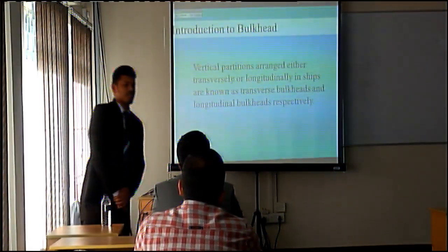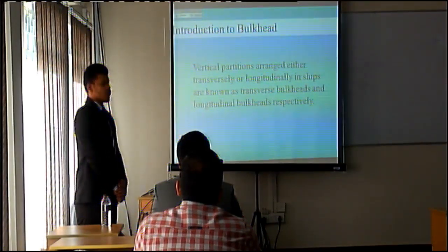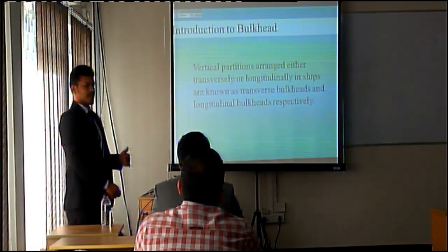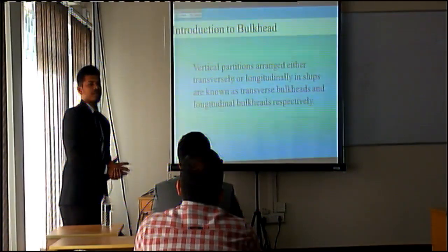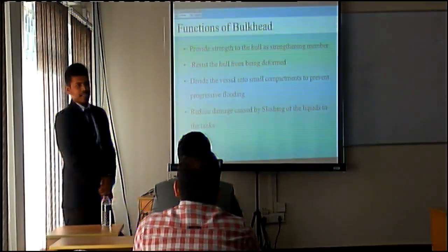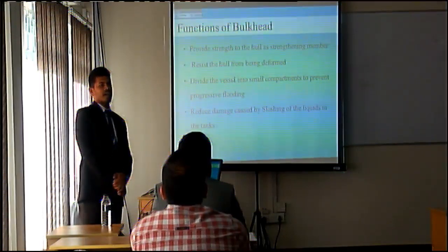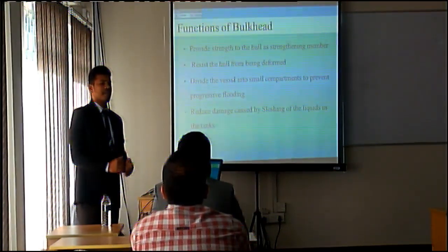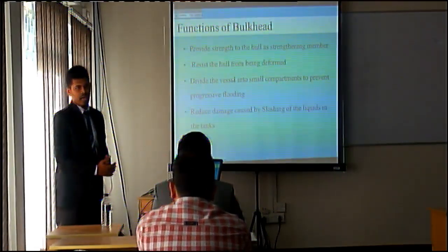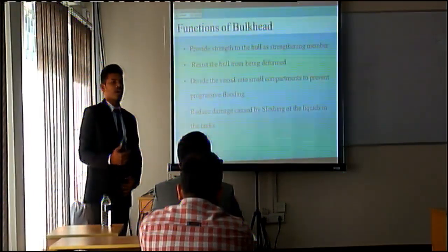For this investigation, we have selected an oil tanker bulkhead from an oil tanker. A bulkhead is generally a vertical structure or partition that divides the vessel or ship into several compartments. There are many functions of bulkheads. Generally, a bulkhead provides strengthening to the hull and resists the bending of the hull, divides the vessel into several compartments, and also reduces the sloshing effect of the oil tanker.